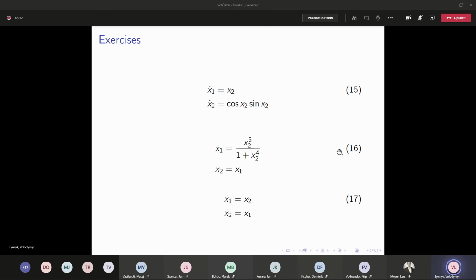The third should be globally Lipschitz because it has a constant Jacobian. Yes, because this system is linear time invariant, and the Jacobian is equal to 0, 1, 1, 0, and LTI systems do not escape in finite time. And the second one?